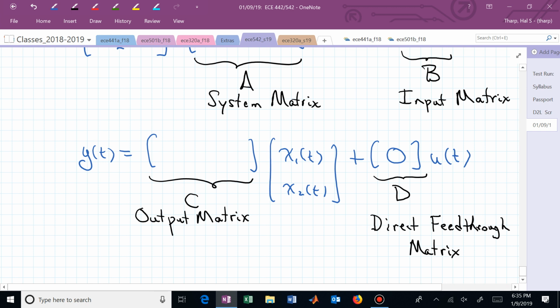So this particular right-hand side better just give us one equation, so it's now one row tall, all of these matrices. How wide is the C matrix? 2. It has to be compatible with the 2 by 1 state vector, and we want it to eventually pull off just x sub 2, and we can make that happen with an output matrix C equaling 0, 1.